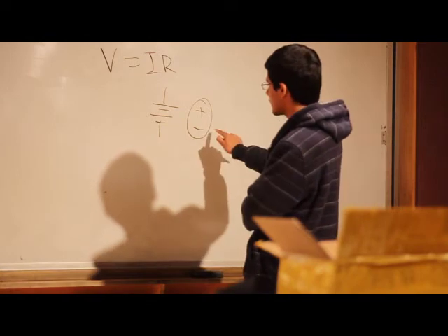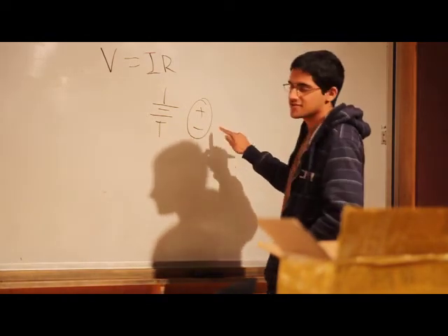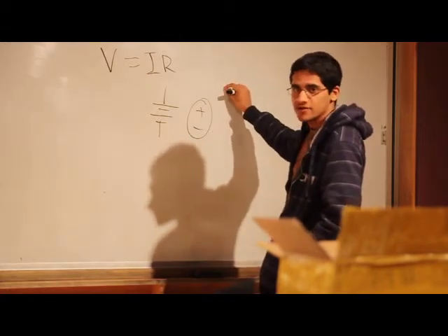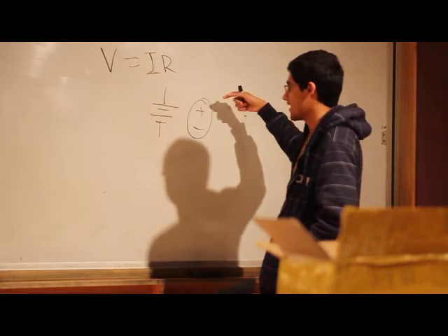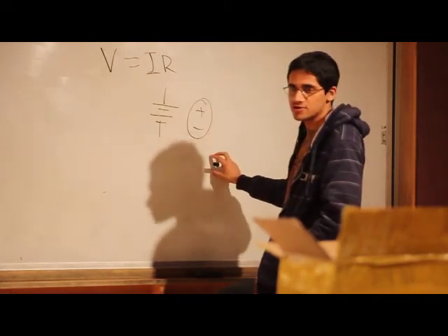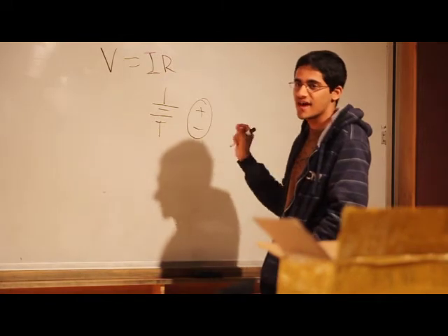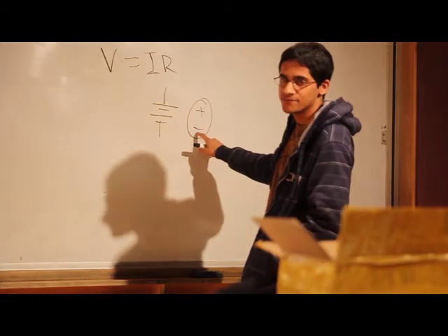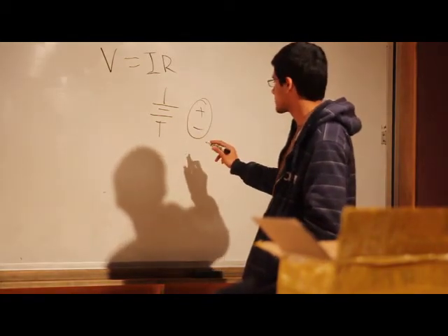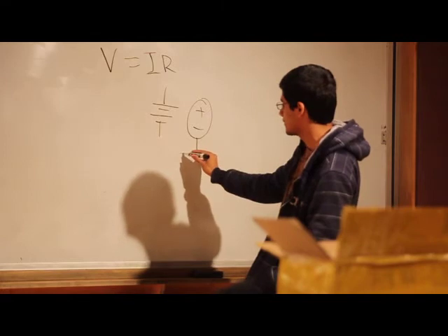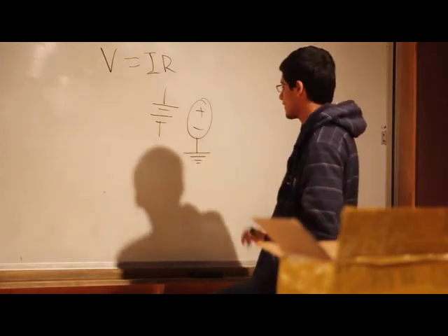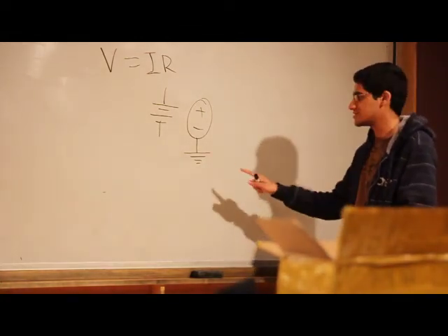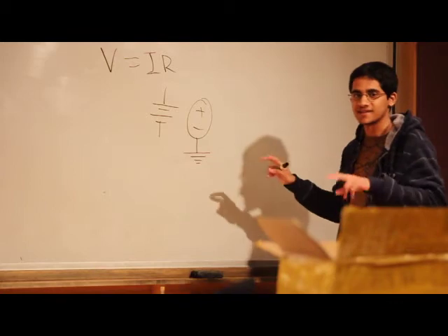So when you draw a battery, you have a plus and a minus. The voltage of this battery is like the energy at one point of the battery, one terminal, and it has another energy at the bottom terminal, and so the difference between those energies is what the voltage is, okay? And so generally, when we refer to this minus sign, in all circuits we usually refer to something called ground, and ground is drawn by this symbol. Okay, and all ground represents is basically our reference voltage. In other words, this ground is what we call zero voltage.